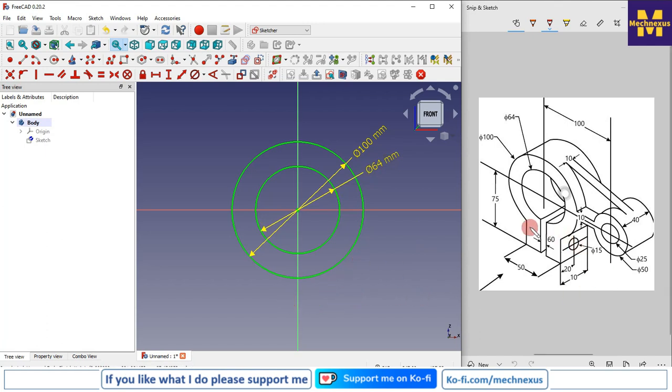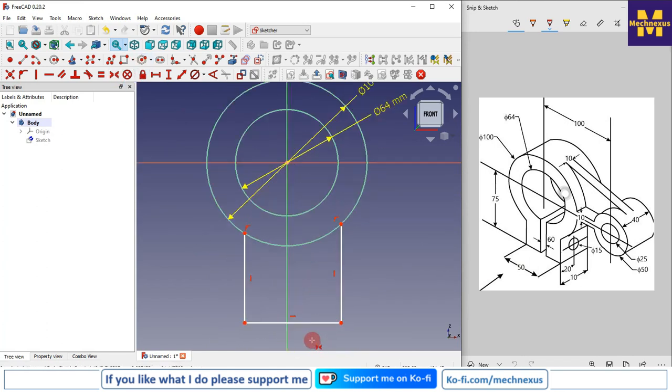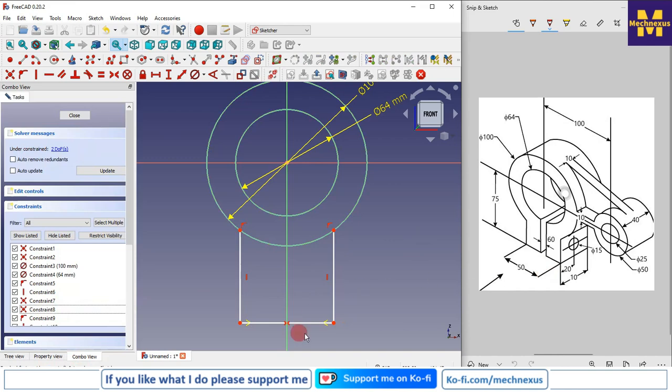And now we will create this profile. So for this I will draw the profile here, and it is 50. So I will select the symmetric constraint, and I will make these two points symmetric with our axis. I will delete this conflict. Now I will give the dimension 50.